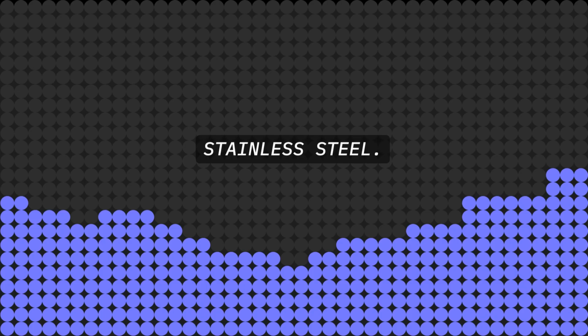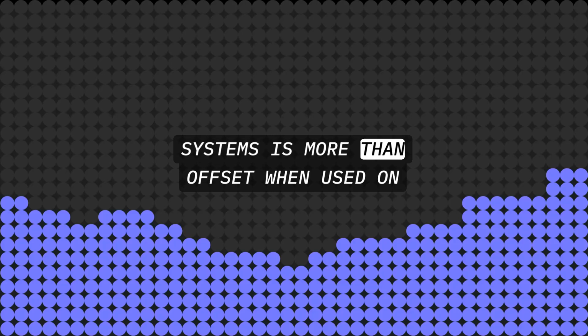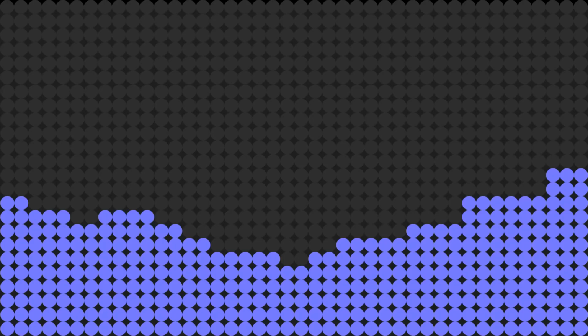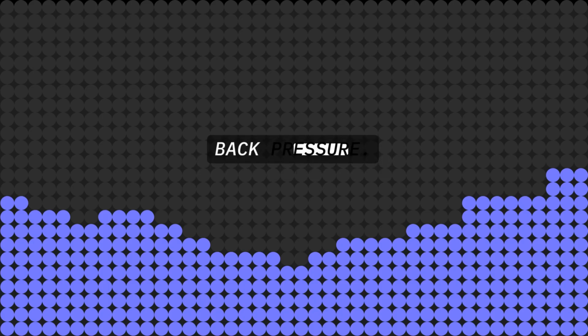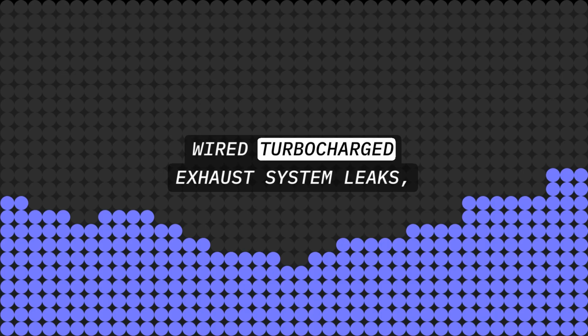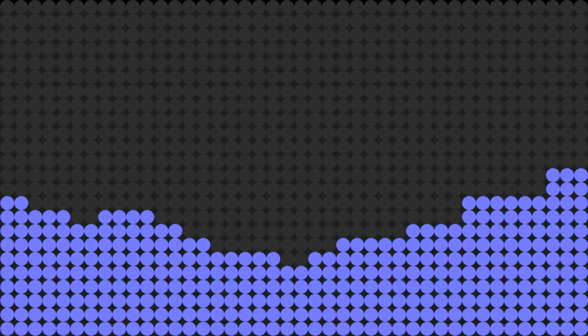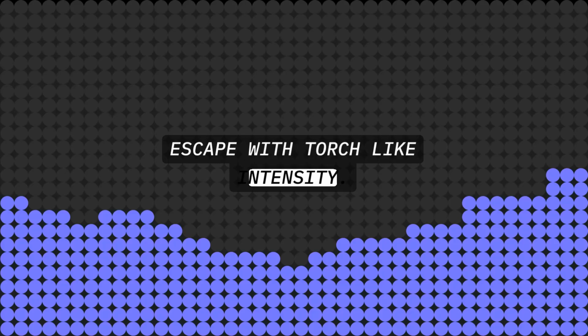Stainless steel. What drawback in using collector type exhaust systems is more than offset when used on turbocharged engines? The loss of horsepower due to exhaust system back pressure. Why are turbocharged exhaust system leaks very damaging at high altitudes? Pressure differential will cause the leak to escape with torch-like intensity.